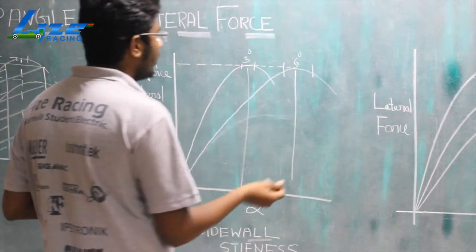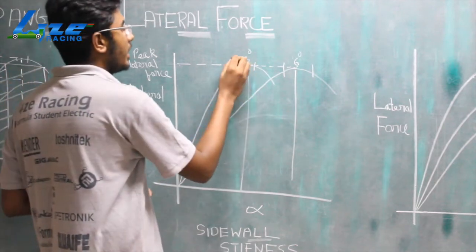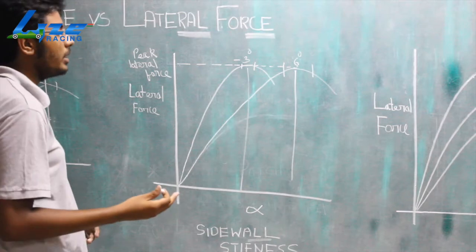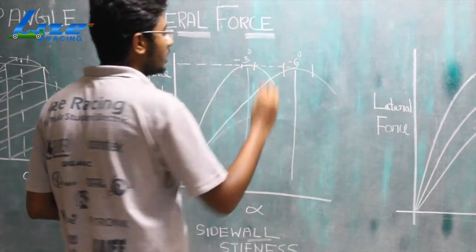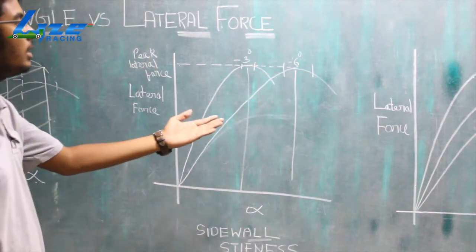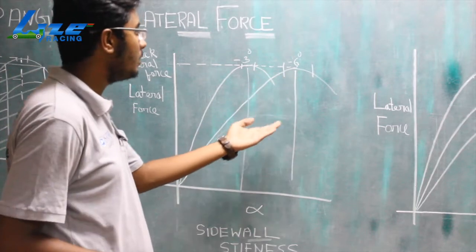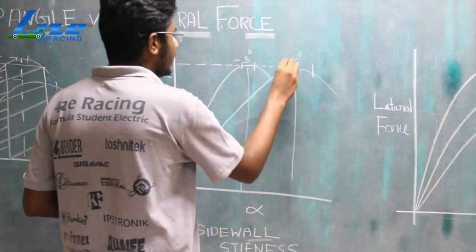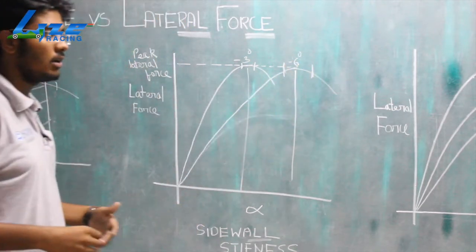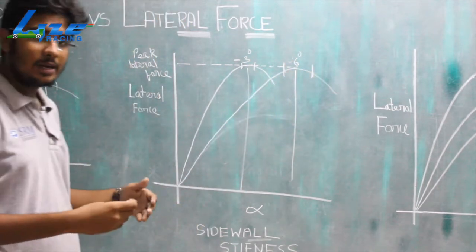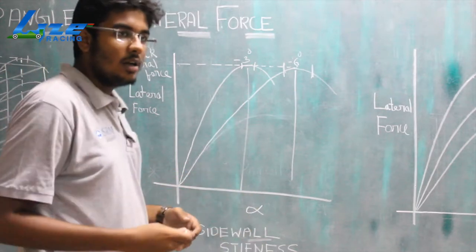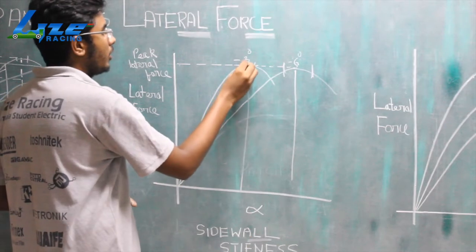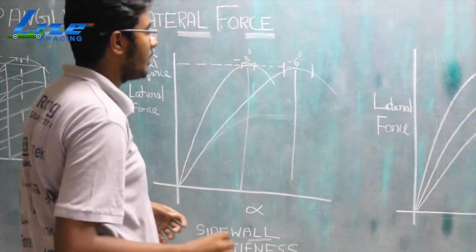But one thing is that Formula 1 drivers drive at lower slip angles. There should be a trade-off, so they are not using these slip angles, because everyone can drive at 6 degree slip angle because it's easier to drive. But if you drive at 6, the heat under the tire or the drag, not the aerodynamic drag but the drag of the tire, is more, and this causes graining. So Formula 1 drivers use the smaller slip angles.